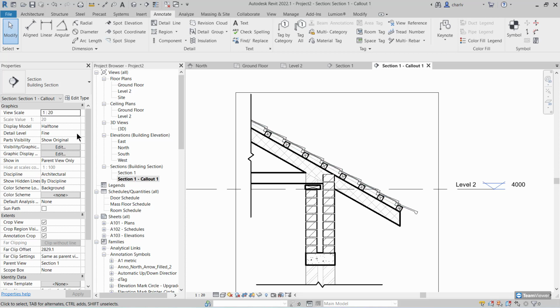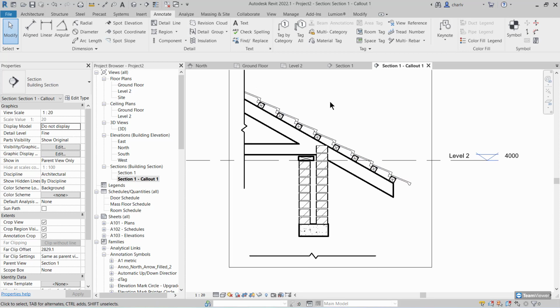2D item, and then at the end, I'll go and say, right, do not show the 3D model. What that then allows you to do is remove the 2D or the 3D model, and so it's now not hybrid detailing anymore. It's just purely the 2D idea. Now, if you stand back and think about it, I've drawn very basic, generic walls and roof. Why? Because changes happen often, and then I come back here, and here is where I put in the actual detail.